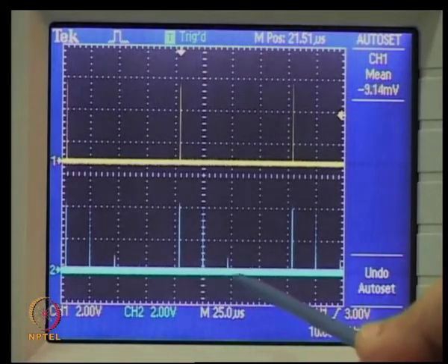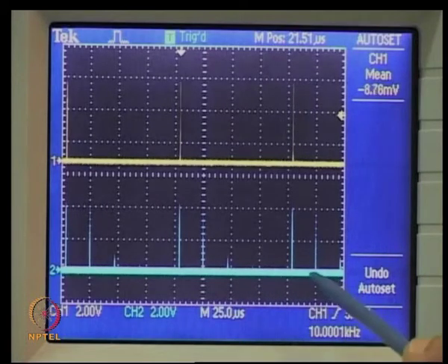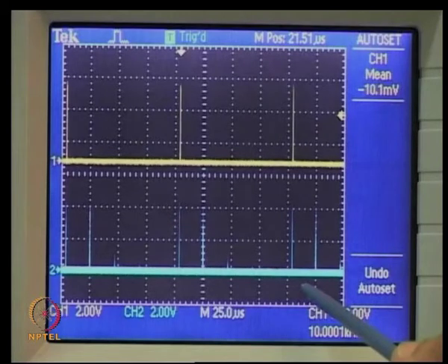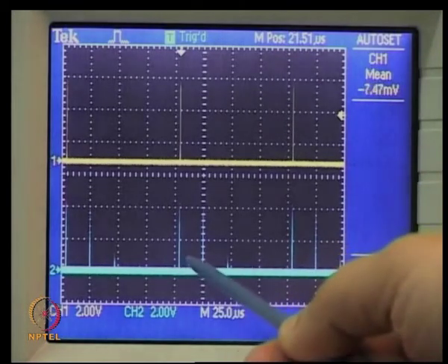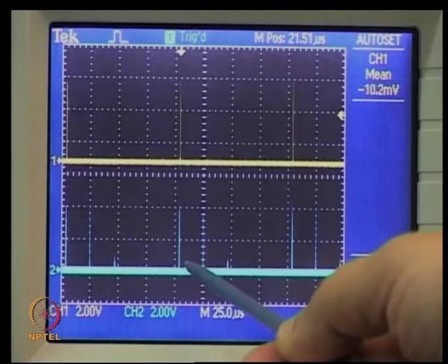Now in channel 2 we can see that there are multiple peaks, each with diminishing amplitude. This is because after each pass of the signal in the 4 km fiber, we get some of the power at the receiver and some is again coupled to the fiber.